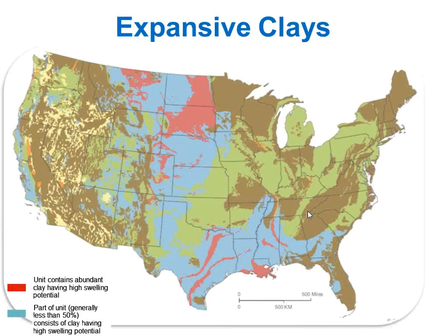Reason number one is because you want to decrease the thickness of your expensive base and keep the same design life. That has been a very good basis for design. There's a second reason. You want to keep the same thickness of your base, but you want to extend the design life. That's another very good reason that worldwide has led to the use of reinforced bases.